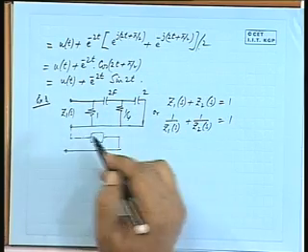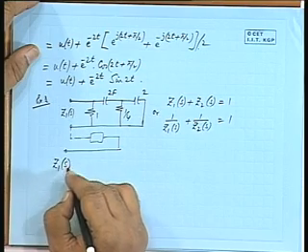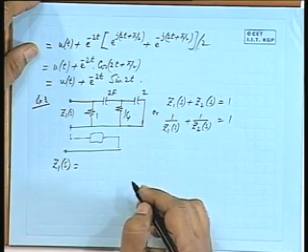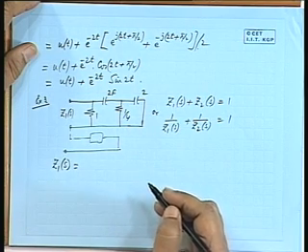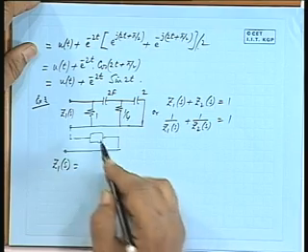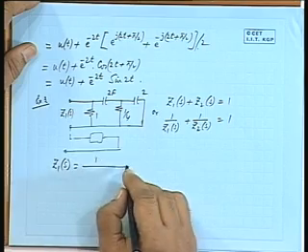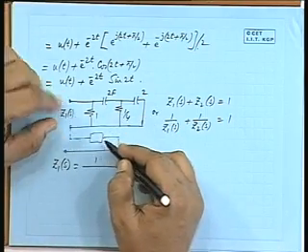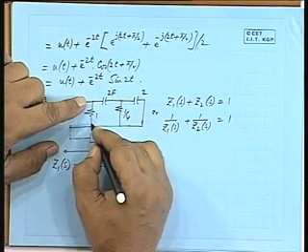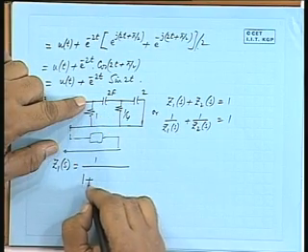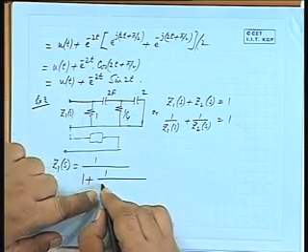So, first of all, let us find out Z1S. Okay. What will be Z1S like? Could you tell me? Ladder synthesis you have seen. Can we try from there? It will be 1 by, if this is ZS, then what is admittance? 1 by ZS. It starts with 1 mho, 1 plus, again impedance. This will be an impedance.